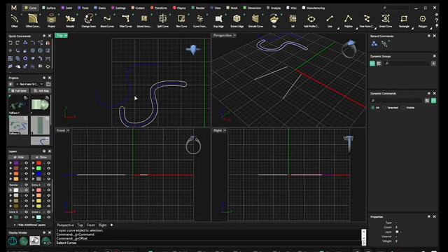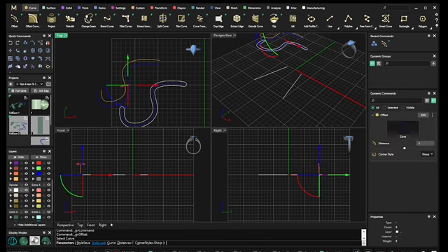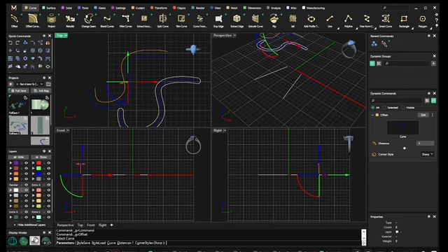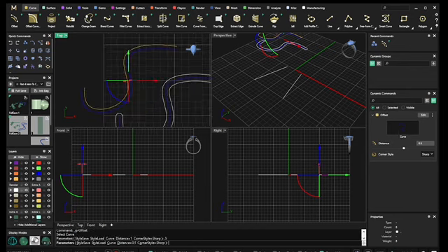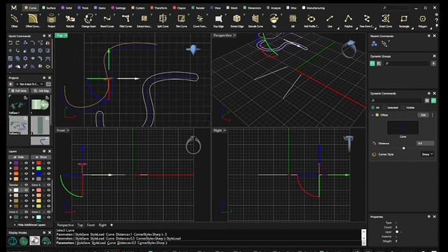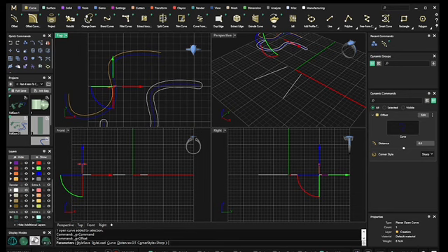So let's try this one. Offset, select curve, and this says 1 millimeter. Let's do 0.5 like we did before. Okay. I don't see where, oh, I'm not over here. It is a dynamic command.